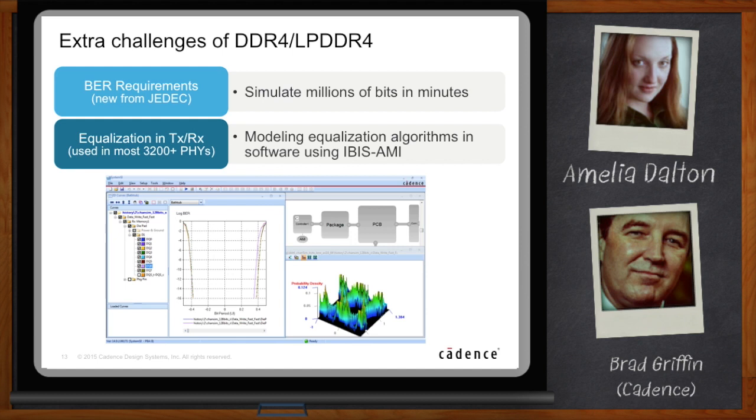And so now we can actually model the boost at the TX or the CTLE at the receiver to make sure that we're able to capture exactly what's happening inside the chip. Because these are things that you don't see on the board, they actually happen in the chip. So you need some kind of algorithm to model that. So we put that in place to support LPDDR4 and DDR4 memory interfaces.